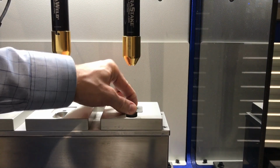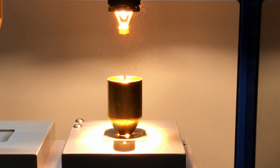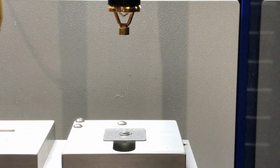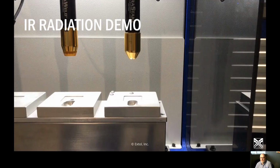But what this is actually showing is we're taking the IR, turning the lamp on, reflecting it down into the concentrator, and then concentrating it on the part. You can see there's a huge air gap here. We're not using hot air. There is no thermal oven. Oh, and you can see we're actually putting enough energy in it that we can make that plastic semi-molten. So what you just saw there is what happens inside of the module, only we do it much faster and much more precise than a hand staking operation.